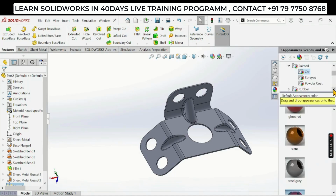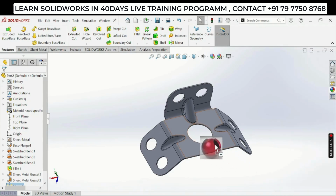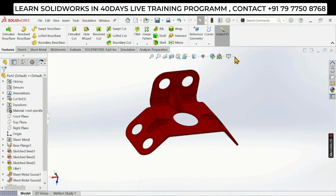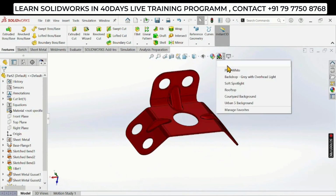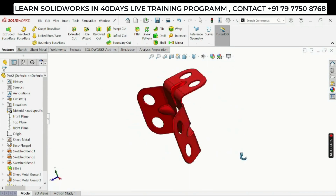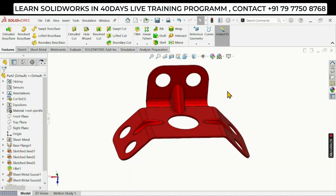Now I can give some appearance to this part. I will select this one. Okay, now you can see this sheet metal. We used the sheet metal gusset command, base flange, sketch bend tool and some sketch commands.